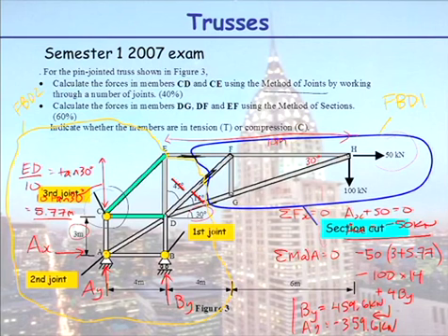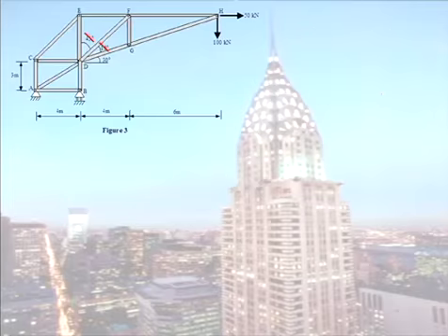If you made a mistake with your reactions and you use free body diagram 2, that mistake would be carried on through. So for this problem, I would consider free body diagram 1 when I calculated those forces. So just setting up that method of sections for you. What you need to do to reduce the chance of making errors is to actually draw.